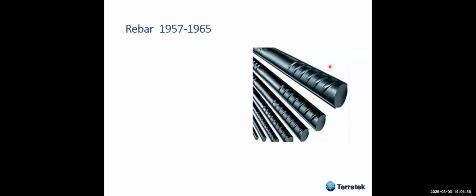Anyway, the first tieback wall I've heard about in soils happened in 1957. I'm going to address this later on. And this type of tieback has been used a lot, more or less until 1965, or perhaps about that time, when the threaded bar started. Most of these tiebacks at this time were 25 millimeters in diameter.